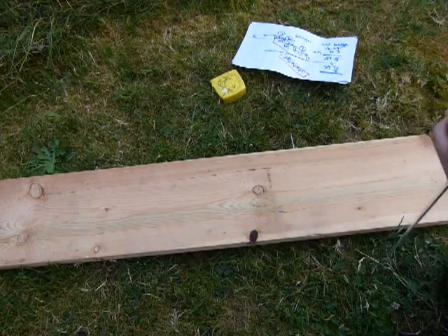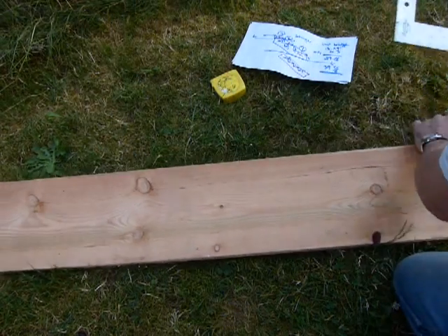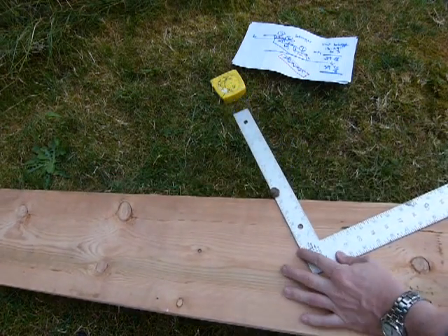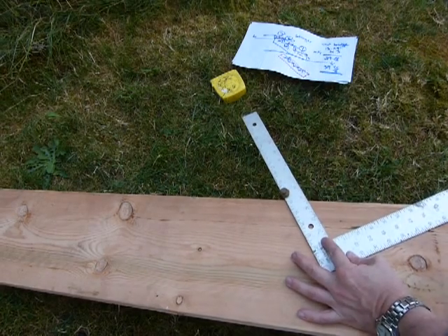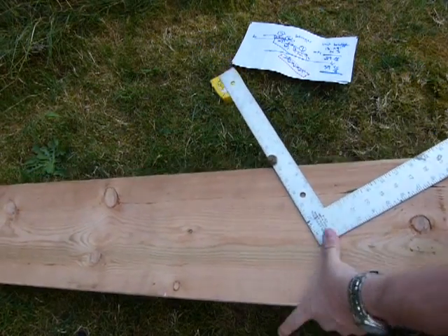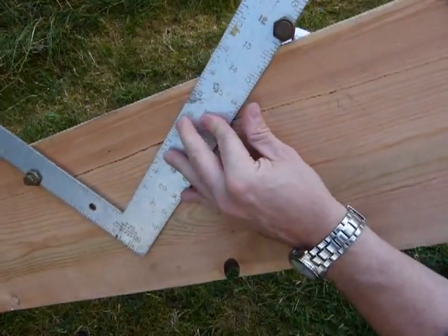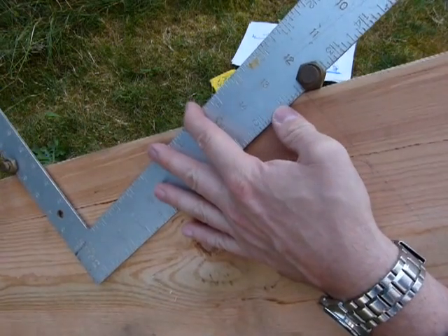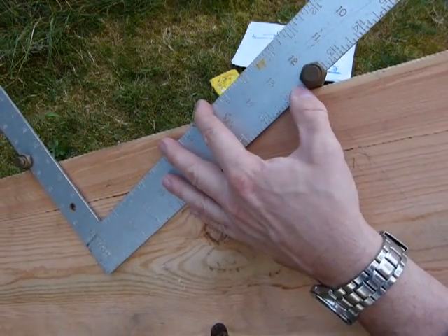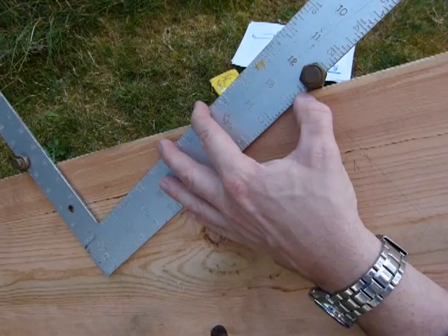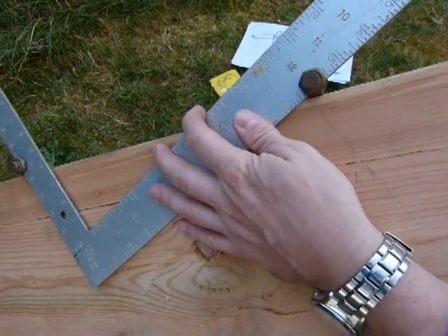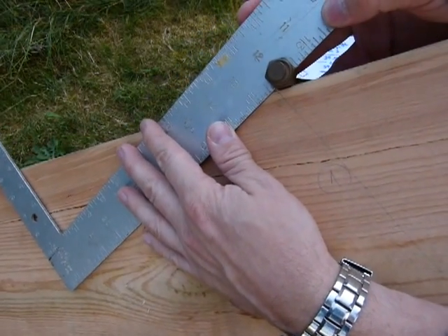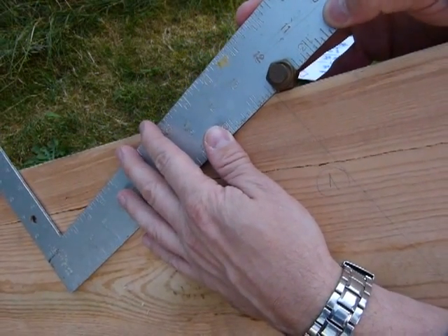I'm gonna do it without my stair gauges on the square. So first I just keep laying out my rises and runs. Take a look here. This is how it looks when I move the stair gauge to the second position. The edge of the stair gauge has to line up with my pencil line, and do your best eyeballing. If it's out a little bit, it's a problem.